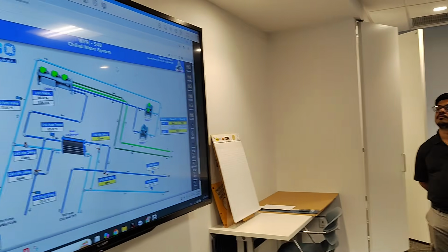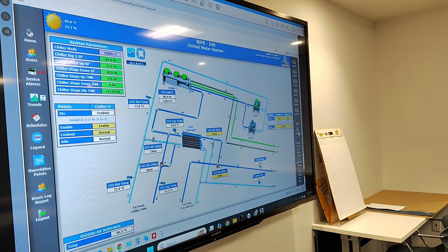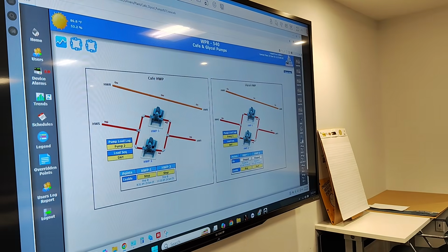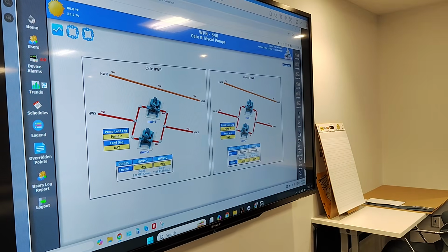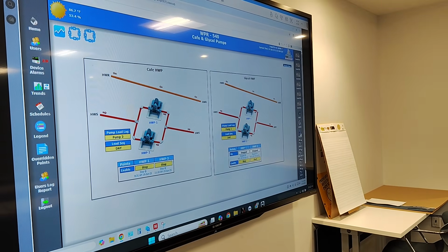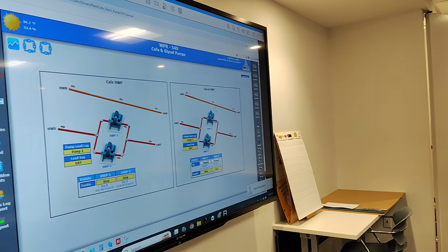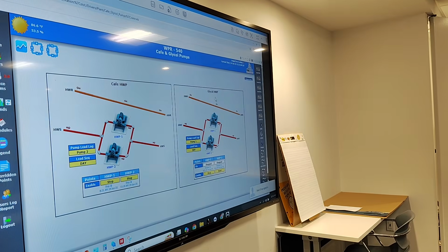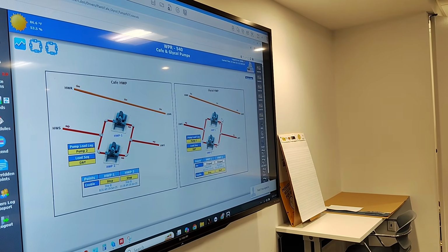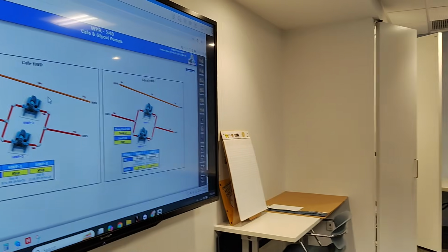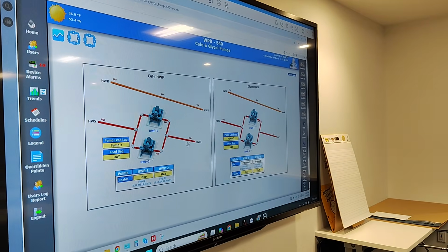Okay, so we're on chiller 3. Let me just go back to pumps. Are these in use? Glycol is not in use. This looks like heating stuff, so all that stuff should be off right now, because we shut glycol down. You also have that outside air temperature set point that starts things. So even if everything was powered up, if the programming is working properly, it should be off. It's off. Glycol's off. Cafe hot water pump.